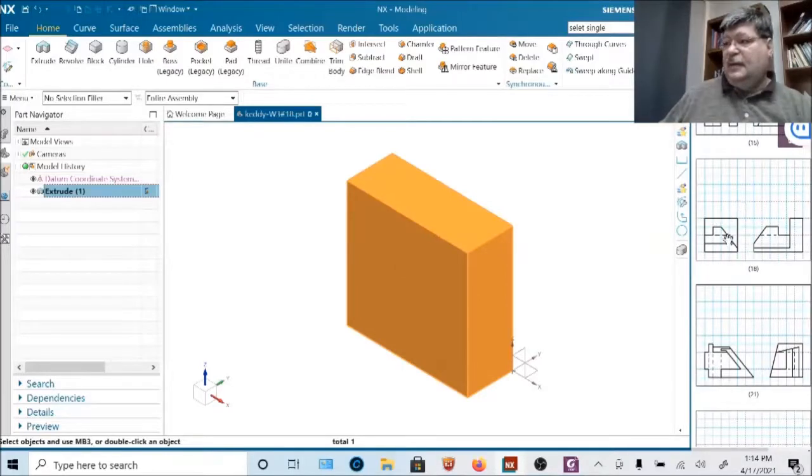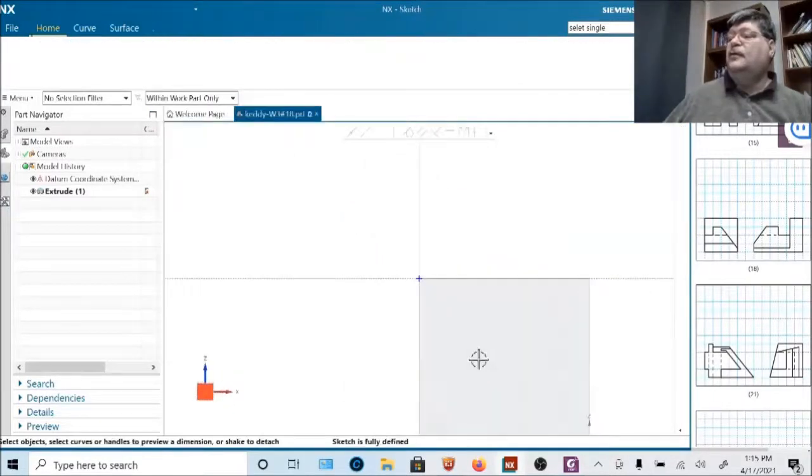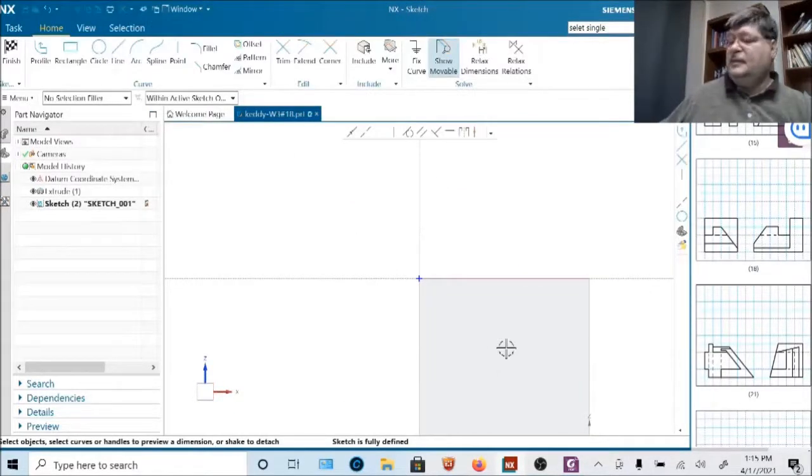Okay, this back piece. Now we're going to do the front. So I need to pick a datum plane and sketch on it. I could pick either one of these 3 datum planes, or now any of the surfaces that we've created, the new planes. Since I'm going to stick this out from this line right here, from this surface, I'm going to pick the front face. So I'm going to go up to Extrude, pick the front face, and rotate it. We are now on that face.